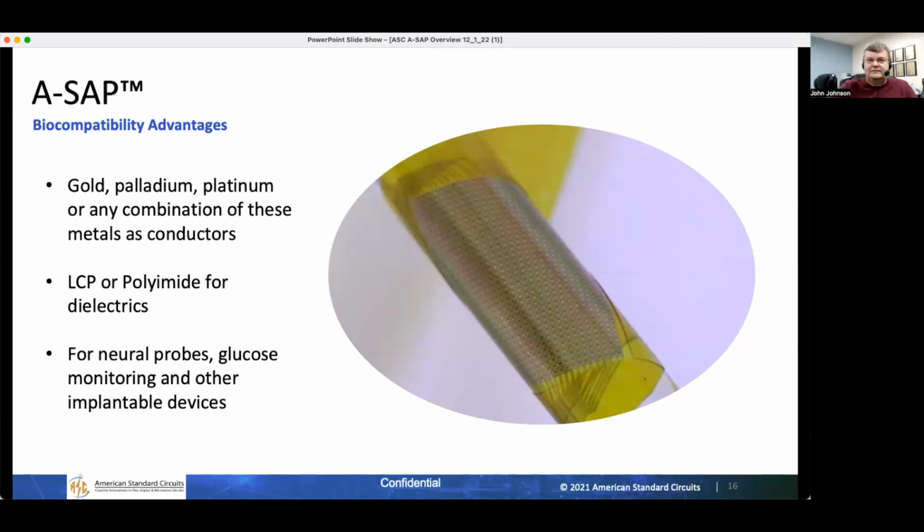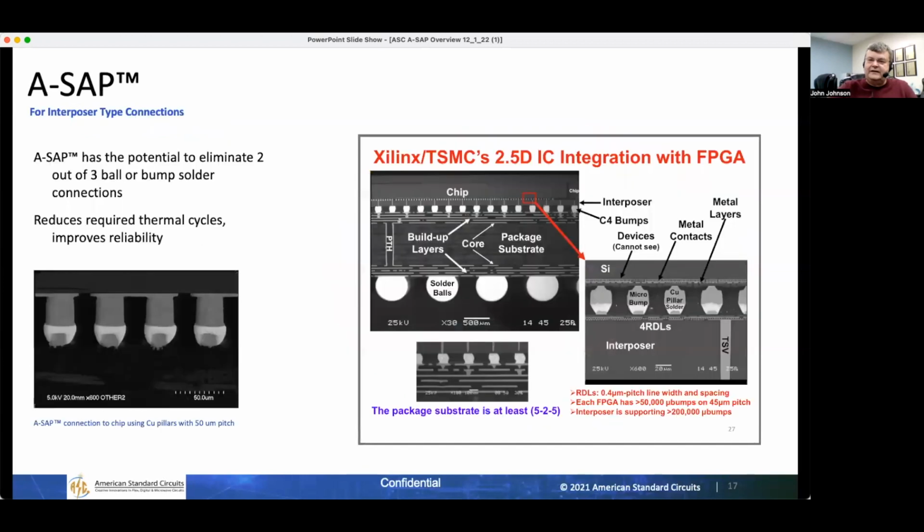Well, we've had a lot of seminars with our customers. Okay. Certainly in discussions like we're having here today, the line is being commercially built, and so that's part of the key, but also in putting together design guidelines and recommendations: things you have to watch out for when you're building parts. ENIG is a great finish, but when you have a 1 mil line and space and you put 2/10 of nickel down, all of a sudden that's a 6/10 mil space. So it does get a little bit more interesting.